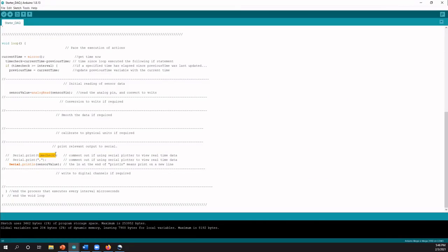And if you try to visualize actual sensor data on a single axis with a giant straight line that says 2000 all the time, you won't be able to see what's going on in the sensor because the sensor data is all very much lower than 2000. So that's why it's purely for visualization. It doesn't break anything. It doesn't blow anything up. It just makes visualization better if, when you're using Serial Plotter, you actually just plot sensor data.